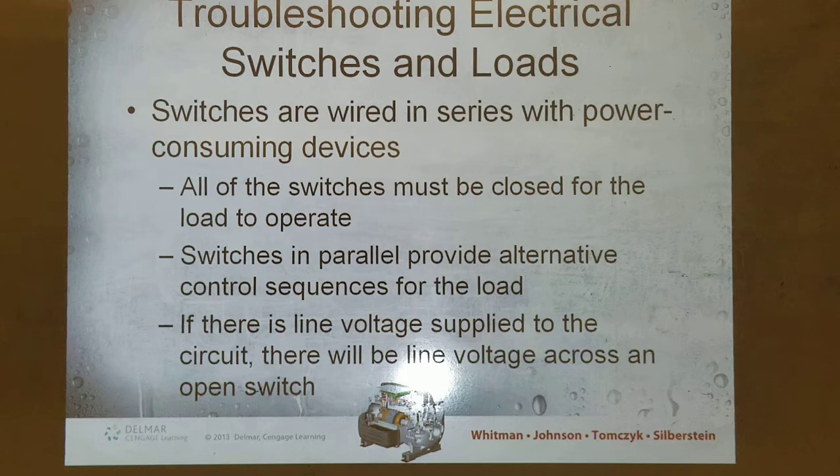Troubleshooting electrical switches and loads. Switches are wired in series with power consuming devices. All of the switches must be closed for the load to operate. Switches in parallel provide alternative control sequence for the load. If there is a line voltage supplied to the circuit, there will be a line voltage across an open switch.